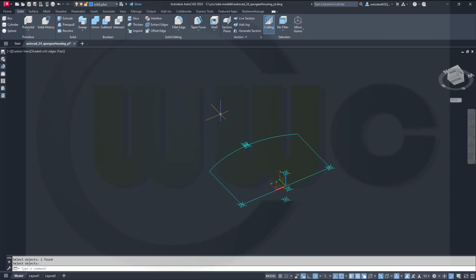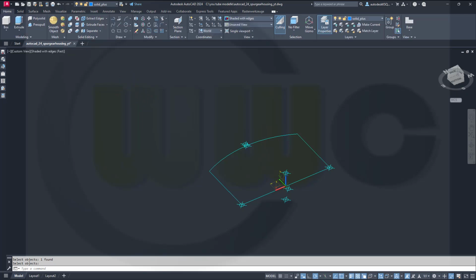Okay, I will need another extrude, but to another point, so I might add 2 more points. Okay, points, go to home, go to draw multiple points, and one should be at 0, column 62.5, and the next one should be at 0, column minus 62.5.